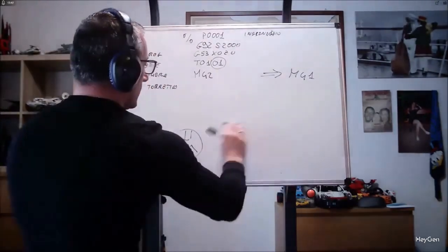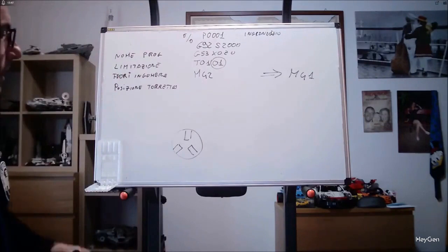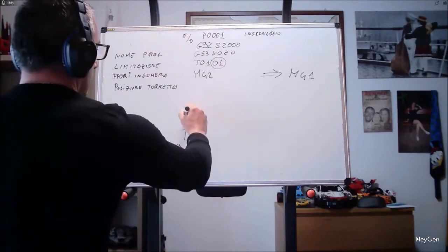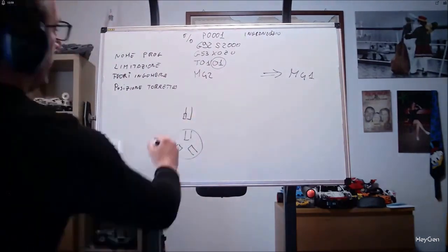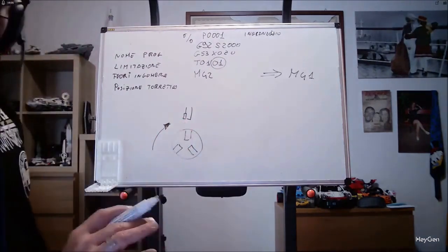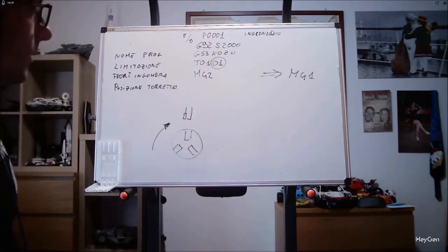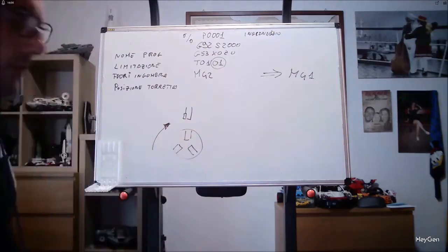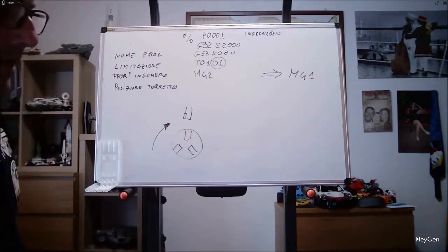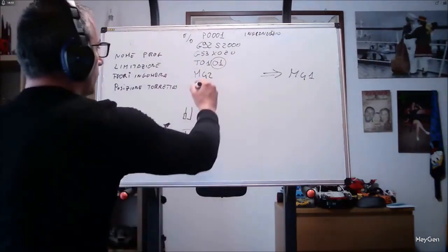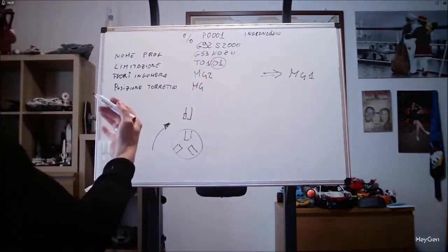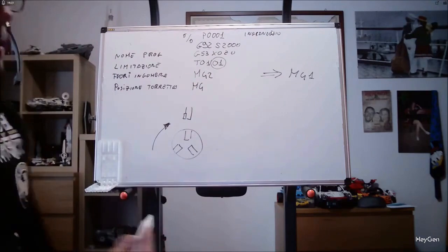Once the range is engaged, this chuck, this self-centering one, will need to be put to work. I am the turret. I am watching the self-centering chuck. This is my tool. The insert is mounted on this side. So I need to work in this sense. This doesn't apply to all lathes because the Italians work in reverse, but for Fanuc, Siemens, or Okuma, the rotation sense for M4 is clockwise when looking at the turret.